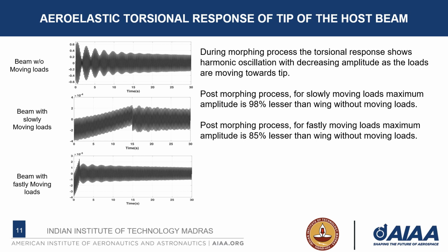Post-morphing process, due to aerodynamic damping, the amplitude of the response decreases gradually. In the post-morphing process, for slowly moving loads, the amplitude is 98% lesser as compared to a normal wing. And for fast moving loads, it is 85% lesser.